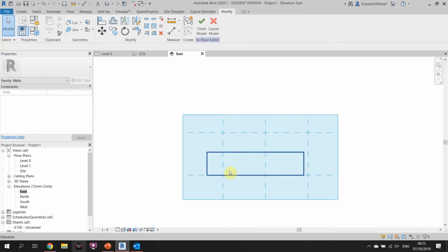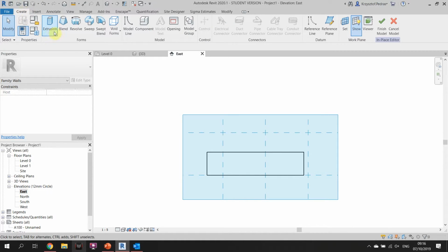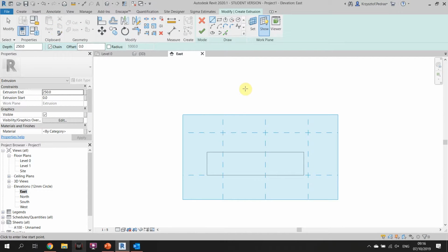Alright, since we got a work plane set up already, we're gonna try to model the mortar. We'll put it on the bottom of the brick and one of the sides of the brick. So later on we can just copy paste the brick and we're gonna have a running bond. Okay, so let's move to the Create tab, and the principle is gonna be pretty much the same. We click Extrusion, and it's gonna ask us to create a sketch of the extrusion that we want.